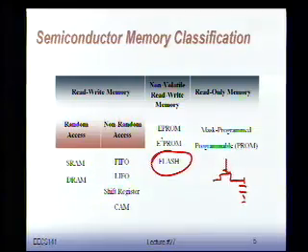That's one example. If I can change the threshold of that transistor, I might make it impossible to write into that cell, for instance. Because if I make the threshold very high, I'm never going to be able to turn on that transistor with a normal voltage. Or if I make it very low, it's always going to be on. It becomes a short circuit.